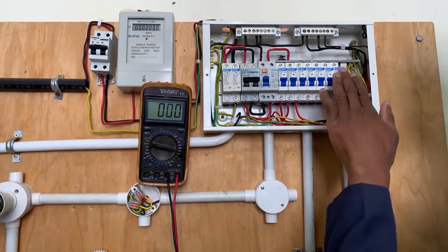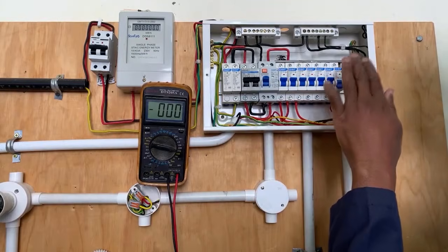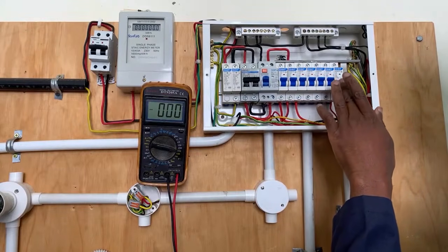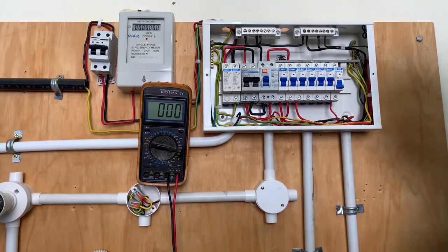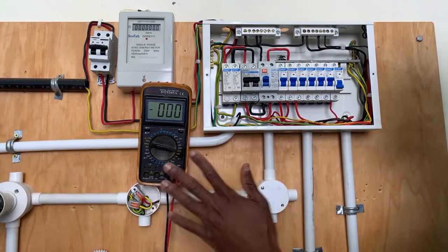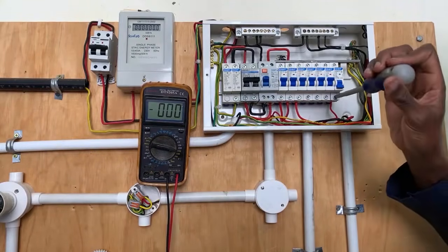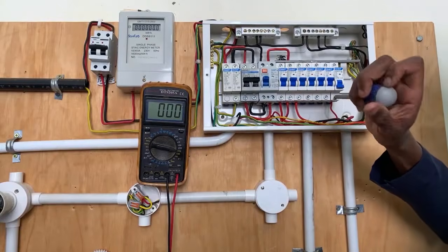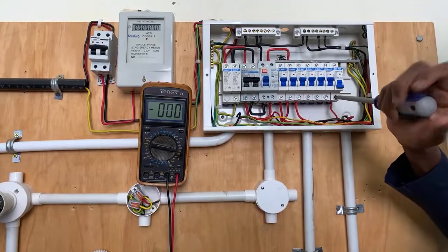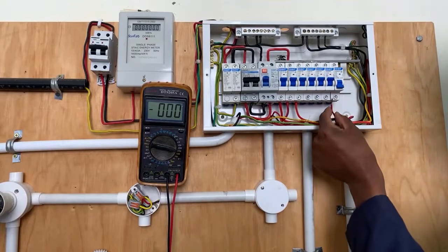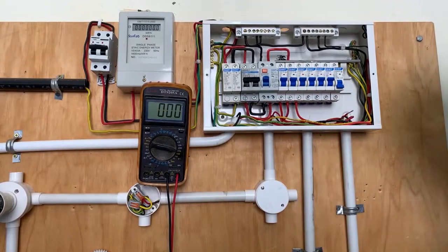Now, because there is a problem and we don't want to put it on, we don't know whether this MCB is faulty. What we will do is to isolate that circuit. They'll say that we have started by isolating the respective lighting points by switching them off. Now, for me, what I will do is to completely isolate the MCB by simply unscrewing that line. So this is the line that is going to that particular circuit.